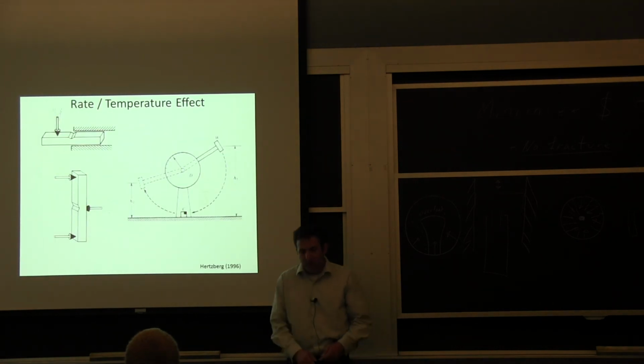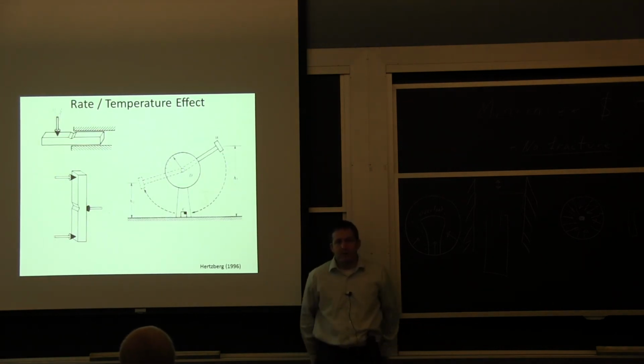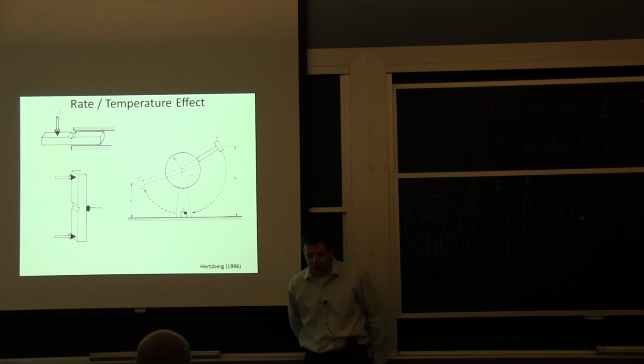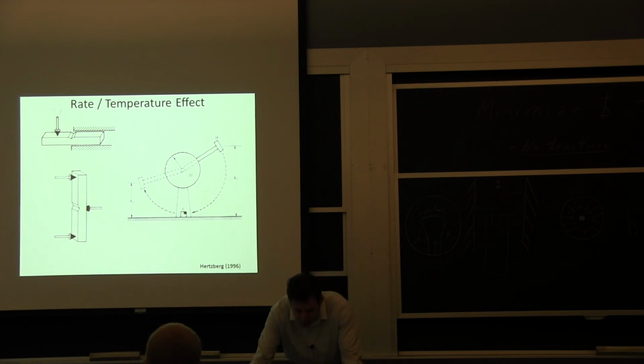All right. So we all know about impact testing, either for plastics or metals. For metals, the most common way is this Charpy V-notch. You can do it normally with these two supports here. So you take a bar of your material.